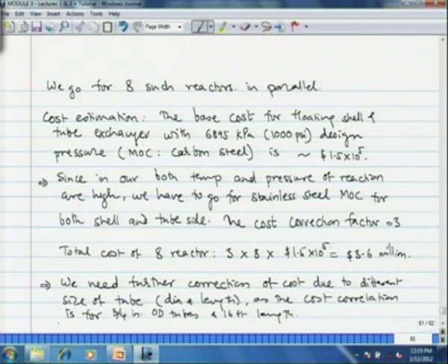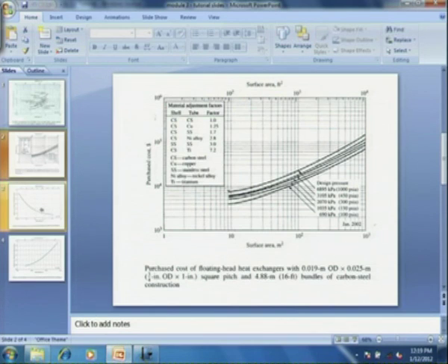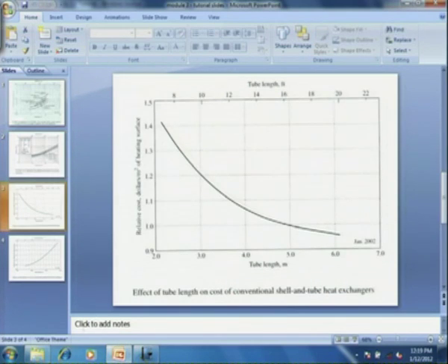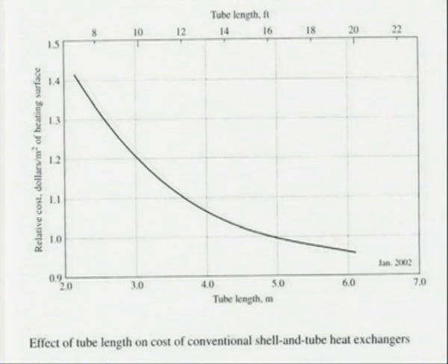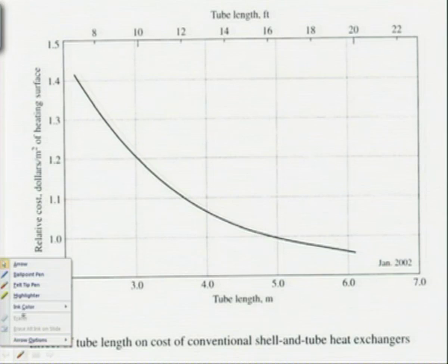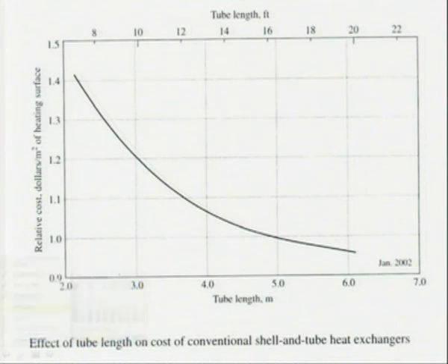Now, we go for the additional correction factors, for the tube length and for the diameter. The tube length in the correlation was 16 feet, ours is 20 feet. So, we have to choose the correction values for 16 feet. These are the correction factors, and then we have to take a ratio.